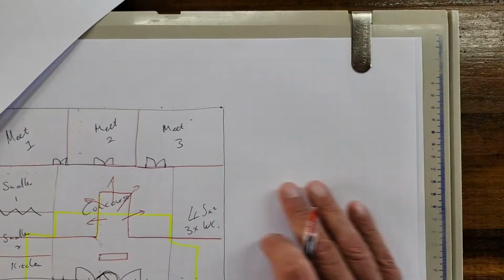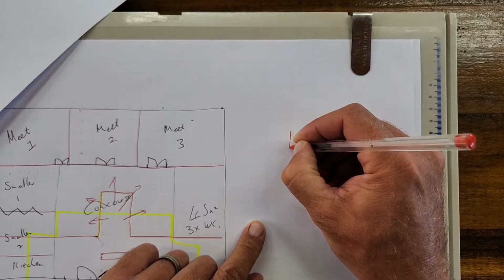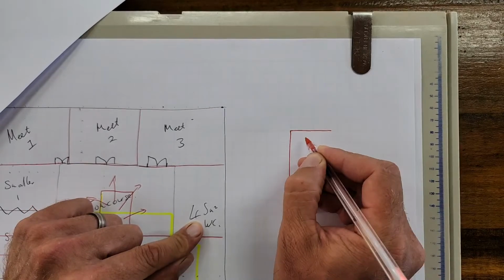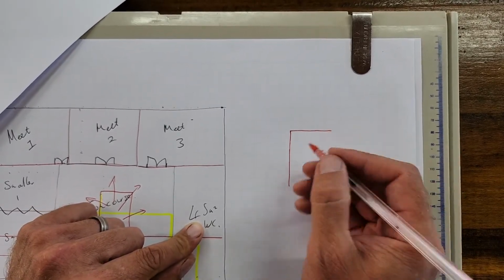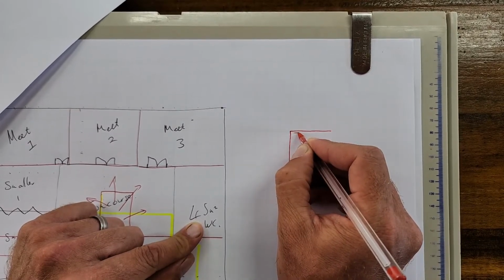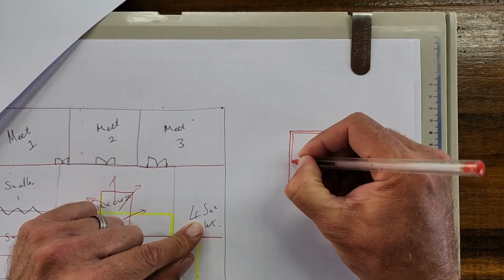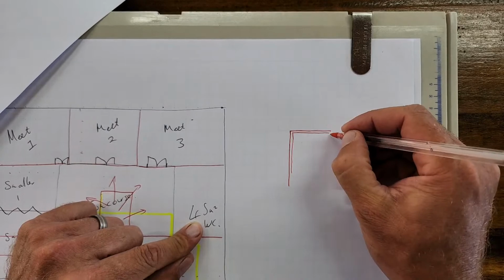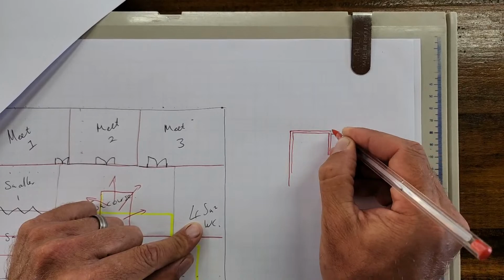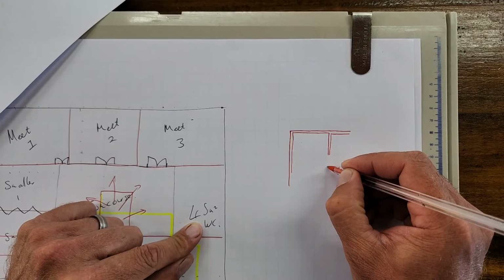But remember, when you're going to start drawing this, you're going to do your walls as follows. Let's say there goes the outer wall. That's the outside of this wall. How wide is the wall? 220. So remember, I only have 1 centimeter here, so in proportion, that outer wall looks about like this. And then you measure each room size. And then let's say your room changes here. Let me just do a room here for the sake of doing a room.